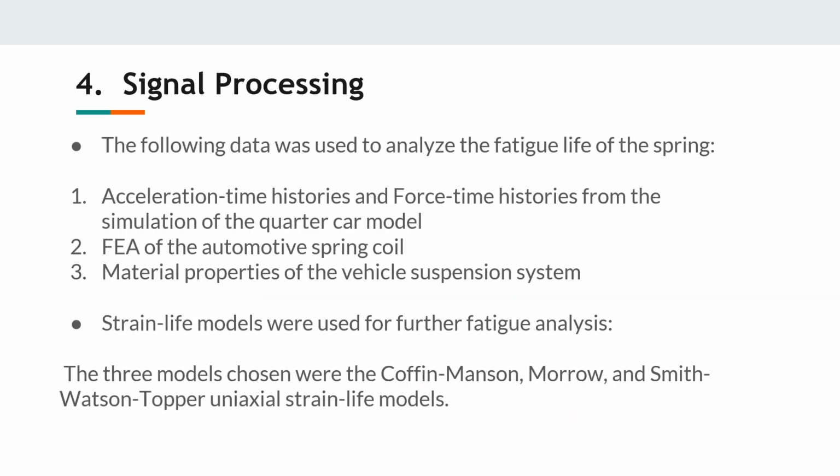After conducting finite element analysis and quarter car model simulation, the data obtained was analyzed. Acceleration time histories of the sprung mass and force time histories of the unsprung mass from the quarter car model simulation were used to analyze fatigue in the coil spring and vertical ride quality. Acceleration time histories of the sprung mass were weighted according to the procedure outlined in the ISO 2631